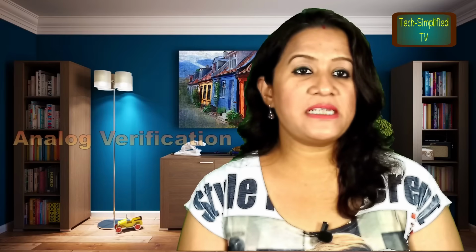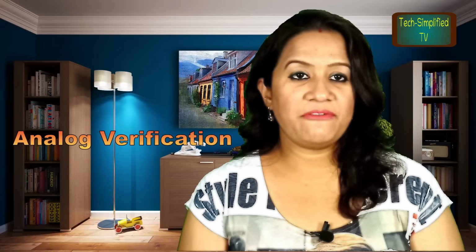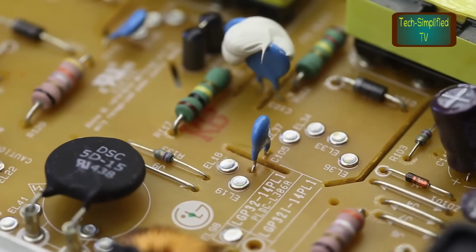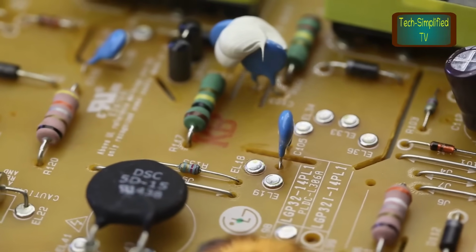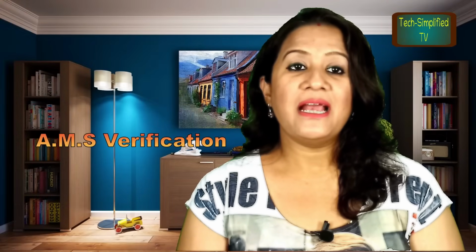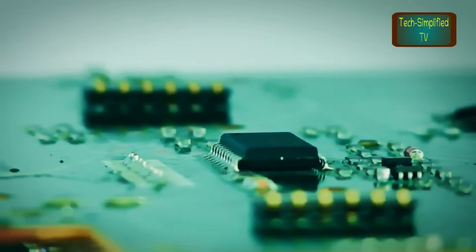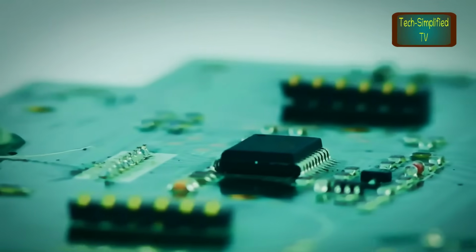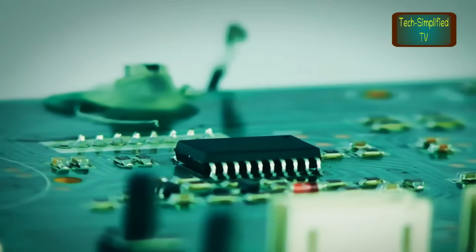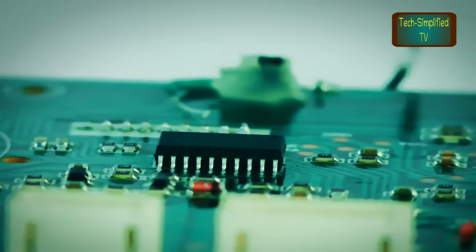Second type of verification is analog verification. Analog verification is a methodology for performing functional verification on analog mixed signal and RF integrated circuits and system on chip. Third is analog mixed signal verification, a single verification environment combining both analog and digital solvers that can be used to functionally verify at the desired level of accuracy using either or both digital and analog engines. Metric-driven verification applies to analog components in a mixed signal design.